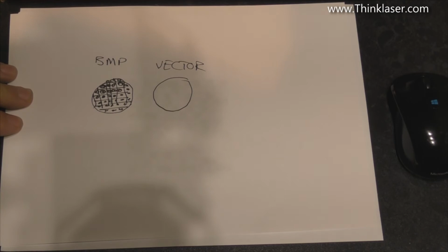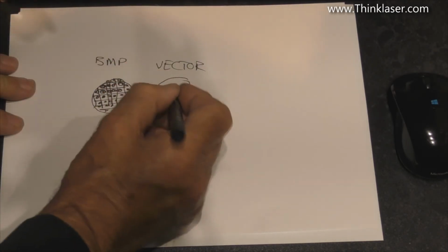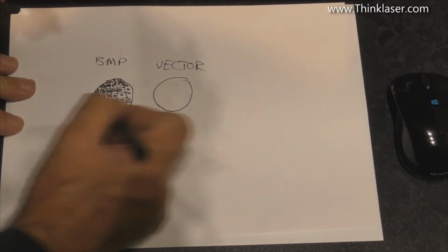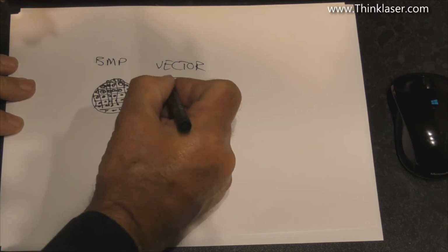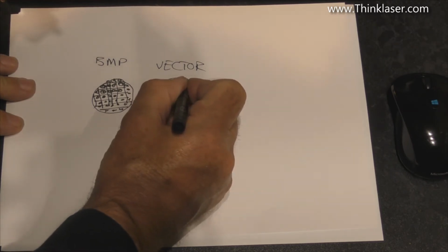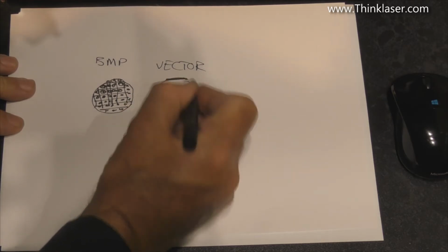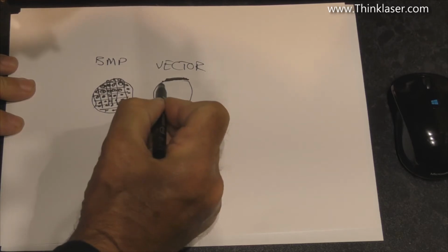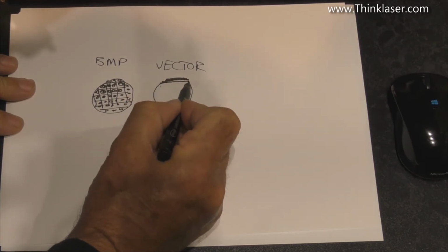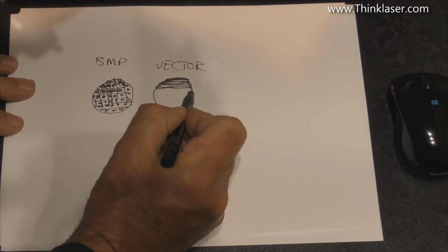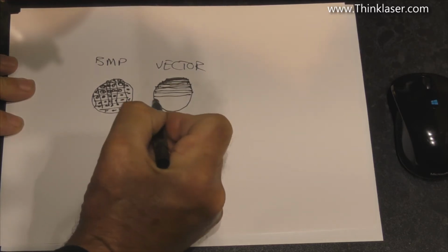Now that's not the same when we've got a vector drawing. The laser doesn't go and put dots on here. What it does, it decides it's going to scan backwards and forwards across this image like this. And as it goes across, it'll draw a line with the laser. So we get a line that goes across there like that. And then it comes back and we get another line. And then we get another line. We do not get dots. We actually get lines that go backwards and forwards across the image like this.